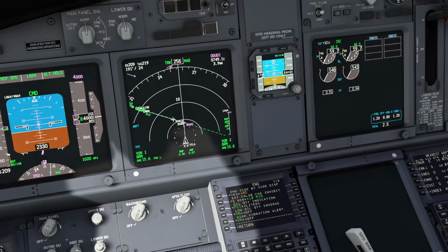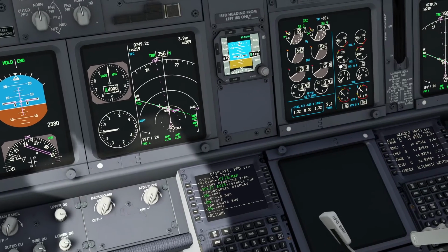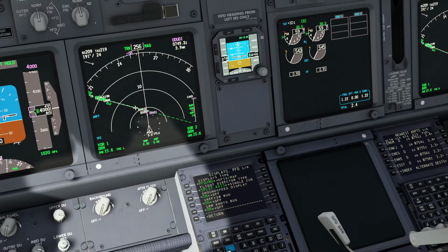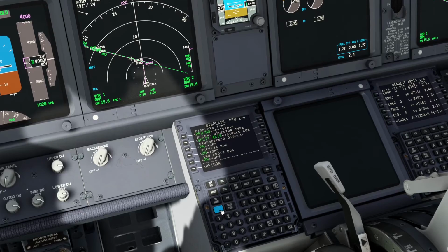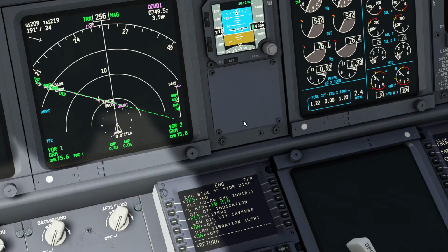Okay, remember that I told you that once you have EFIS and map, you will have this type of engine instruments. So this is the only option that you have for the EFIS map display panel. But if you have PFD and ND, you have the option to have the same information for the engine. You can have them side by side.